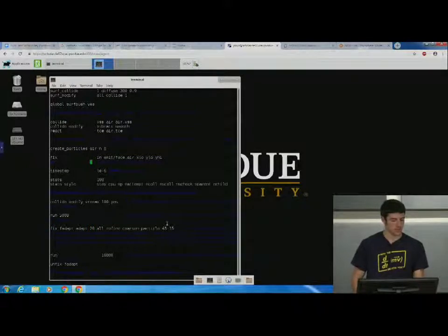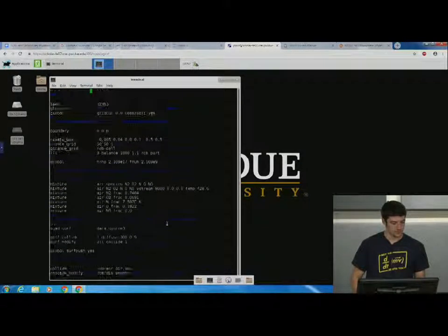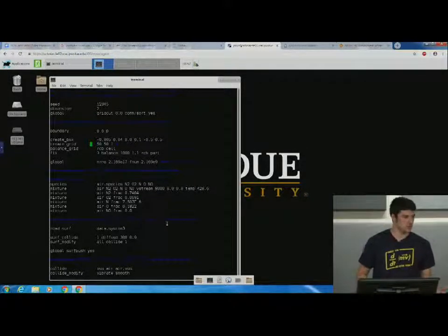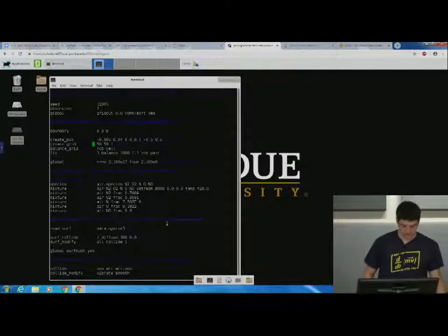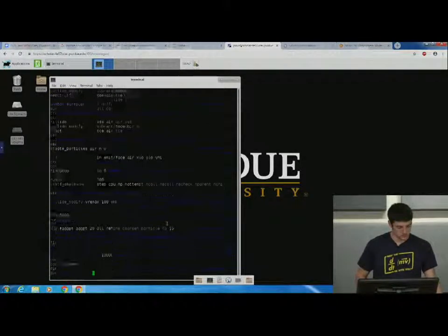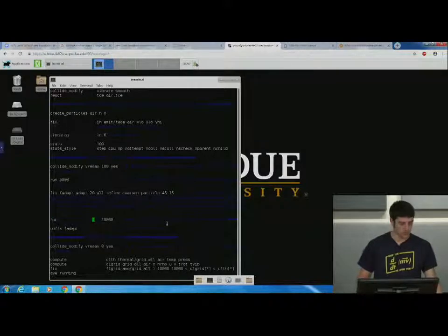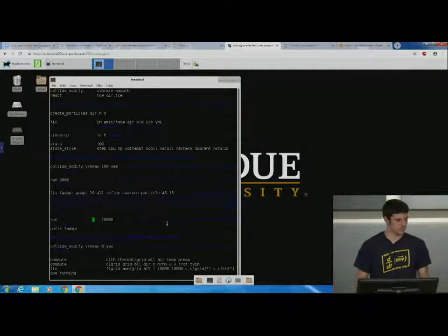And certainly the nice thing with this is you can start off. If I go back to my create grid here, this is my level 1 mesh, 50 by 50. That's pretty coarse, but that's okay because I have this coarse mesh to start off, and then I'm refining it to make it much finer. Also, one thing to note is your level 1 is as coarse as the mesh will go. So you can specify level 2 and level 3 mesh to make it finer, maybe give your mesh more flexibility. Then I'm saying, run for another 10,000 time steps, and this lets it refine the mesh, and that way get a more optimized mesh for the problem.